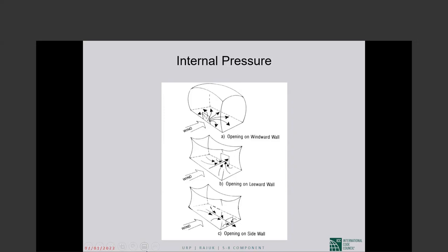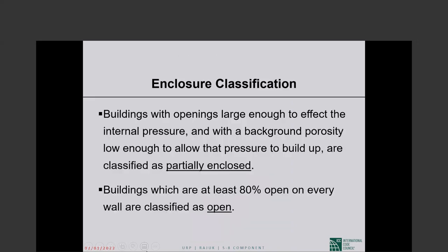The side face is a suction face. So again, we have negative internal pressure. So we can have positive internal pressure, we can have negative internal pressure. In design, invariably, we always consider both possibilities, both internal positive pressure and external positive pressure. Okay. That brings us to something extremely important that you absolutely need to understand.